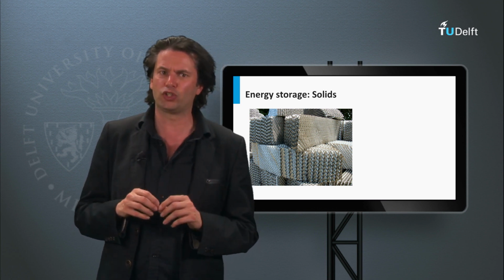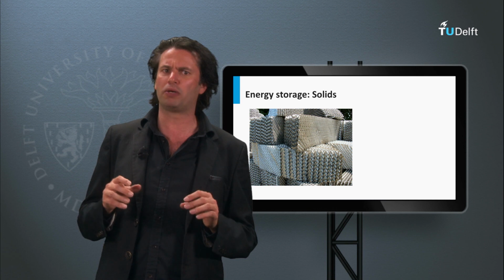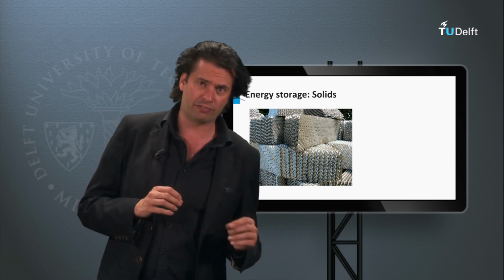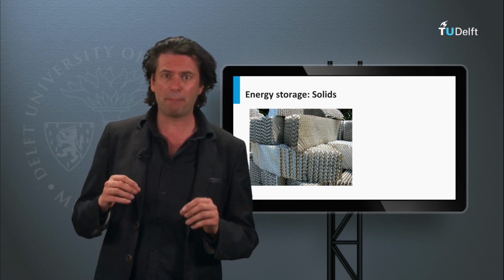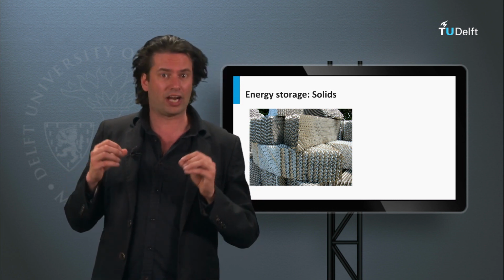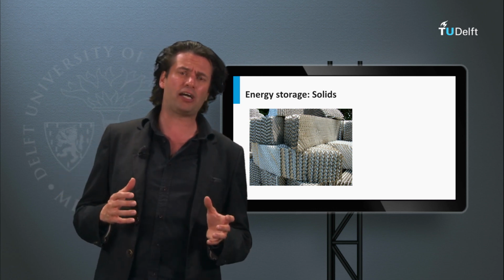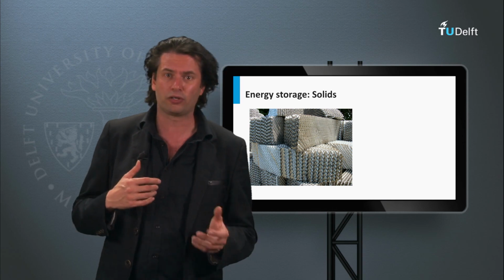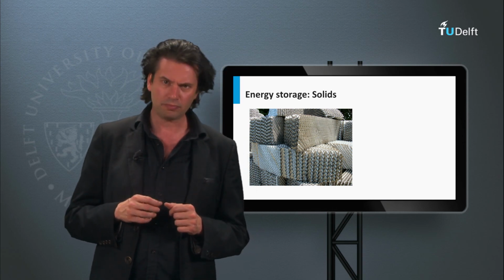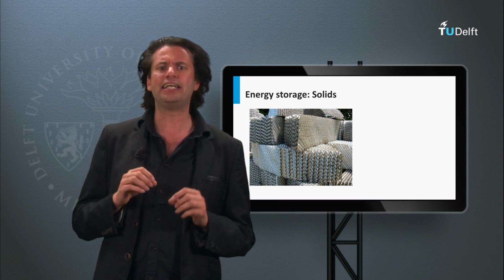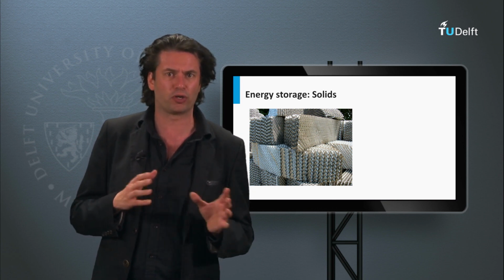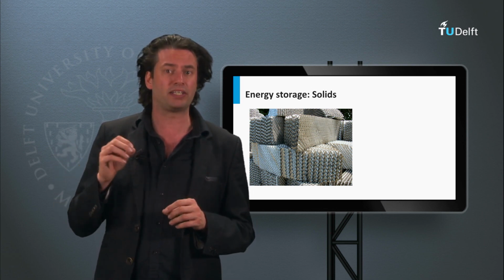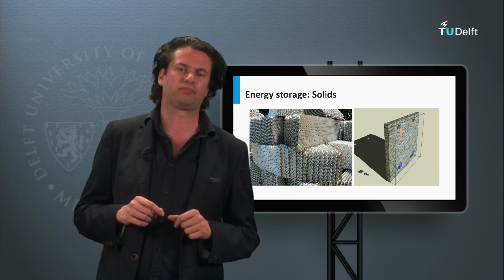A packed bed in a solar heating system does not normally operate with constant inlet temperature. During the day, the variable solar radiation, ambient temperature, collector inlet temperature, load requirements, and the other time-dependent conditions result in a variable collector outlet temperature. The bed is in general heated during the day with air from the collector, and energy is removed during the evening and night by air temperatures near 20 degrees Celsius flowing upward.